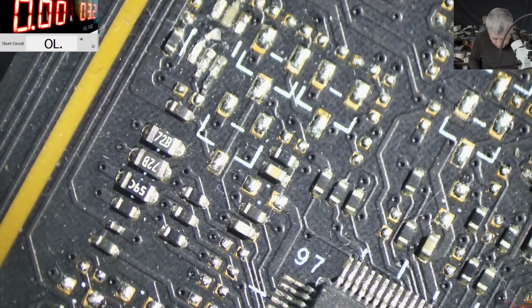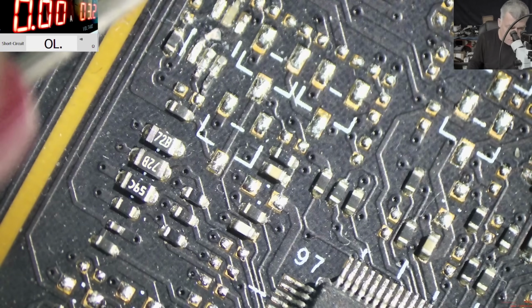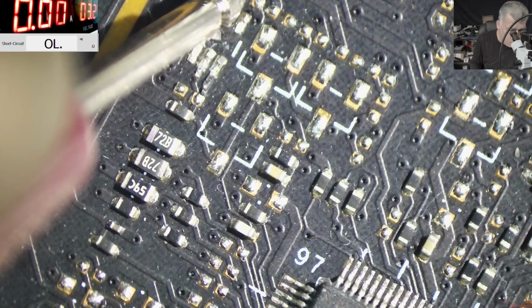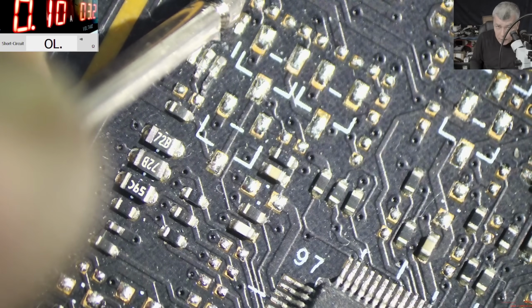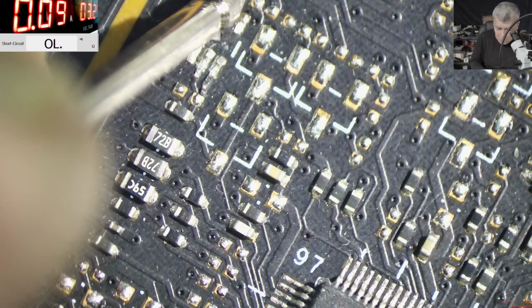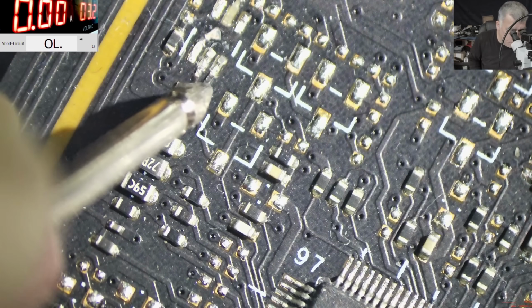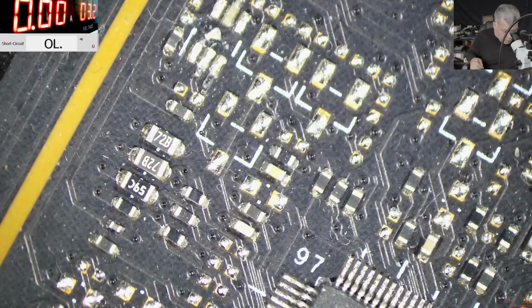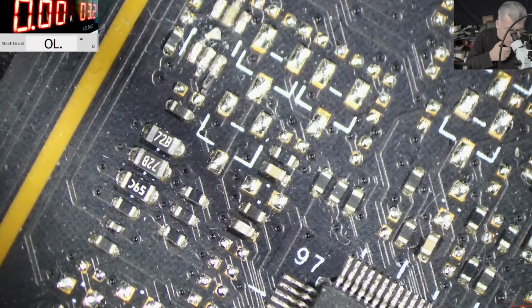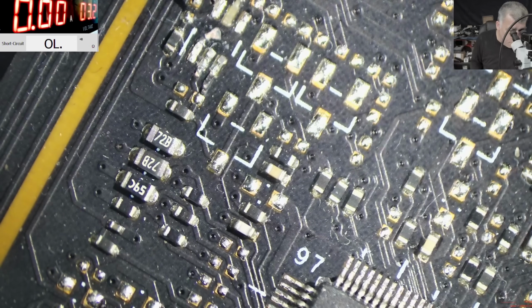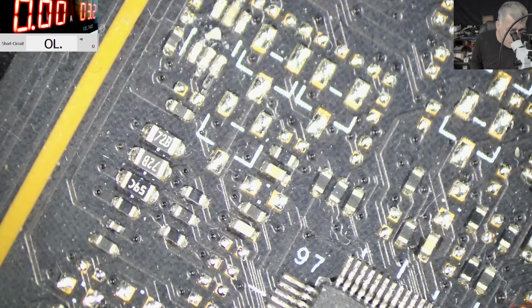And no, the board is not... oh, sorry, I was pressing the... okay, one more time. 100 milliamps, pressing the power button, and nothing happened. Good. Actually, it's not good, it's bad, but let's say it's good. So this pin is not a high amperage pin. Okay, I will try to short this pin to ground.